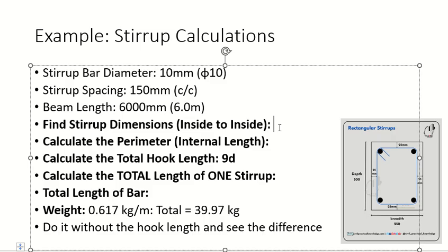We call it concrete cover, clear. If you don't leave enough gap, now remember, where is the load? On concrete, right? If you don't leave this gap, because of the load there can be some cracks, and these cracks can directly go to the steel. And leaving less gap will make concrete weak here.